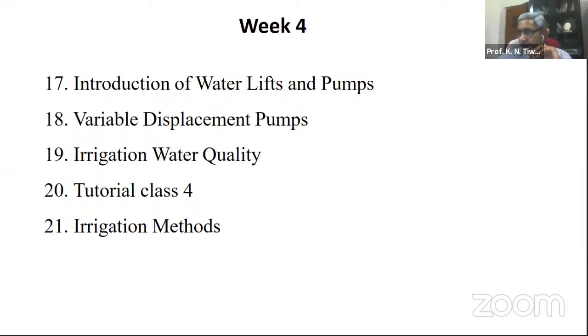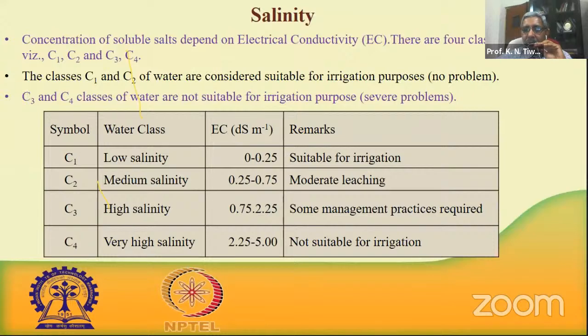Mr. Karthik, thank you for your question. When we are talking of water scarcity, particularly in water scarce regions, you may find that water salinity is also a problem. In order to use saline water, the surface method of irrigation has a problem because you are flooding the whole field. In a drip irrigation system, you can use saline water to a certain extent. I don't say a very high value of salinity. So 4 deciSiemens per meter is recommended. Some crops like brinjal, eggplant, give a better response with saline water as compared to fresh water.